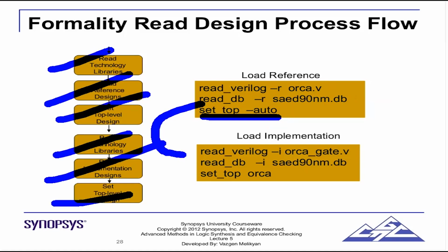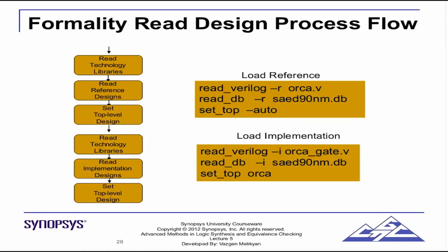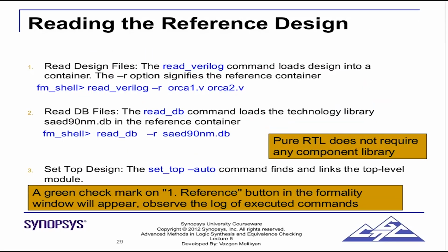If your RTL does not use any cell from the technology library, this step is optional, only when the reference design is RTL and does not use any hand instantiated cell. You might be using memory, so here you will also read the memory DB. Next, these are the commands: read design file, read_verilog, read_db, set top. Again, pure RTL does not require any component library.